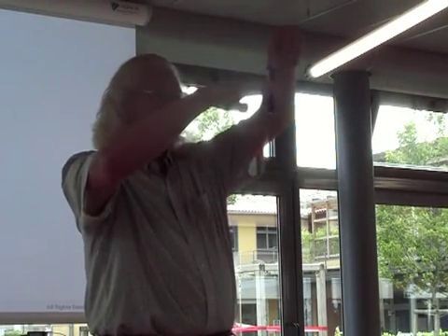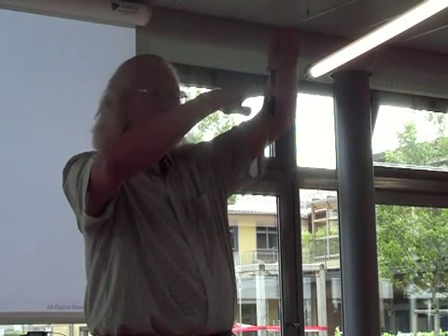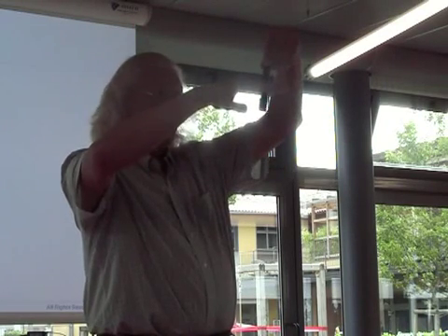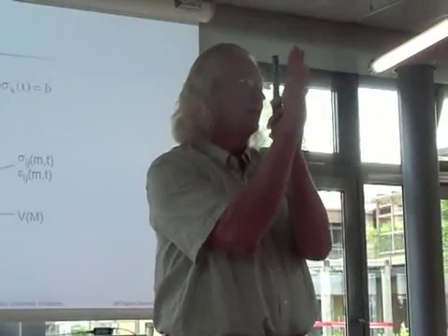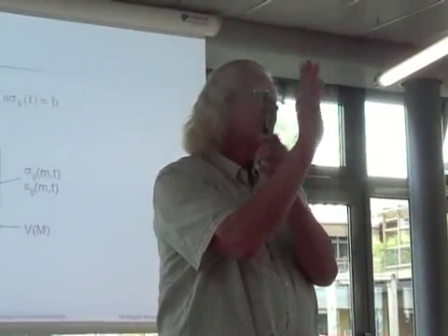Stresses act on planes, and so if I think about a plane like this, of course the tensile stress on that plane is 10. And if I think about a plane which is oriented 45 degrees like this, then the stress is 5, both the tension stress and shear stress. And if I need 0 for the answer, then I choose this one. I told you I am tricky.